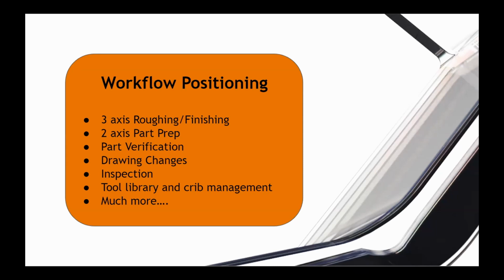So just giving that extra piece of insurance to program an inspection feature to make sure that the boss is actually machined before we take the part out can save you a ton of time and a ton of headache of, oh my God, we missed the feature. I have to put this part back in just after I machined it, right?